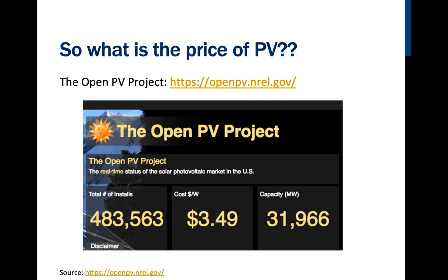So on the high end, a solar electric system, utility intertie, no batteries, is going to cost around $3 a watt or less. The more complicated it is, or the further away it is on a ground-mounted system, the higher that cost is going to be. The more straightforward it is, the lower the cost. The shop I work for takes on all the complicated systems, residential and commercial, and so our shop charges a premium for that. So we're at or a little bit above $3 a watt.